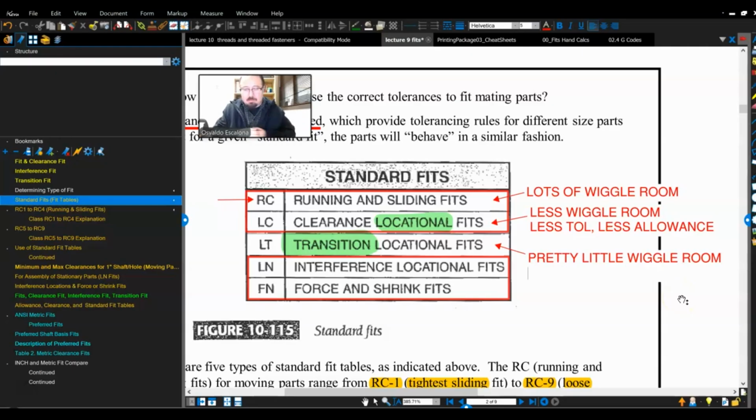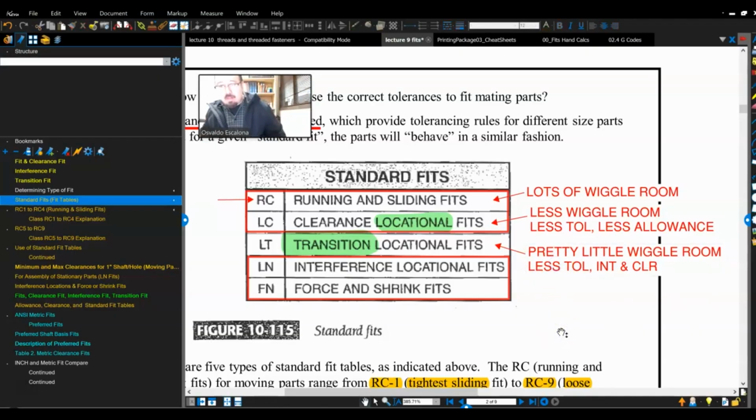And again, I will still have less tolerance, way less tolerance, right? So now I'm messing with things. And again, in this case, I'm actually going to have an interference in the clearance condition. You guys remember that this is the transition. We call it the push fit. When you can put it inside, it's a little bit hard to put inside, and it's a little bit hard to put out. Push fit. And they say, okay, so now that will be the one.